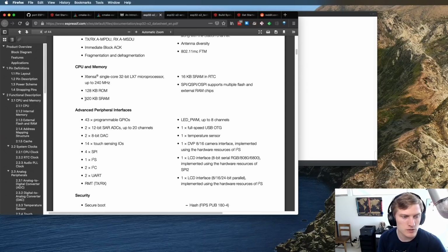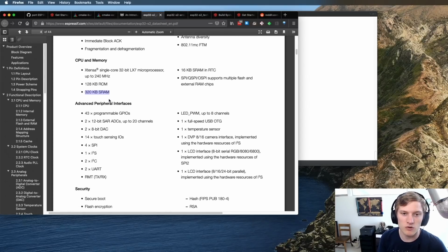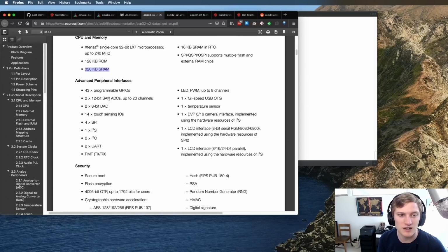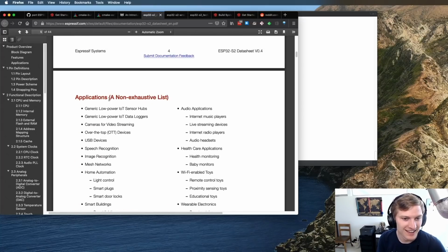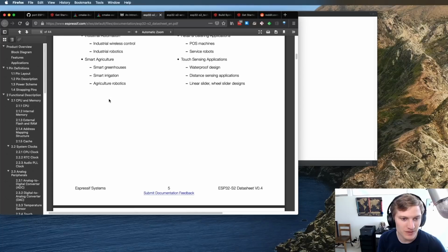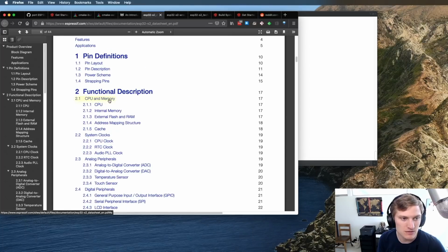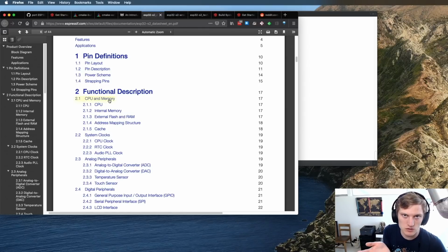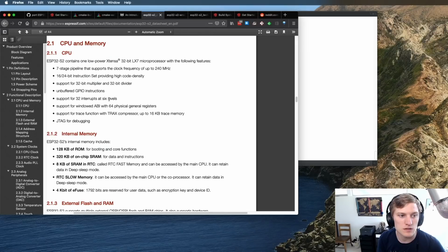So this 320 kilobytes of SRAM is valuable memory space because it's on board the chip, which means it's much more likely to be faster than external PSRAM. People are like, oh, 4 megabytes of PSRAM, that's great, but it's all slow. You can't access it very quickly. And so in CircuitPython, we've started to designate the core VM stuff as critical, and we actually place it closer to the CPU itself so that it can run faster.